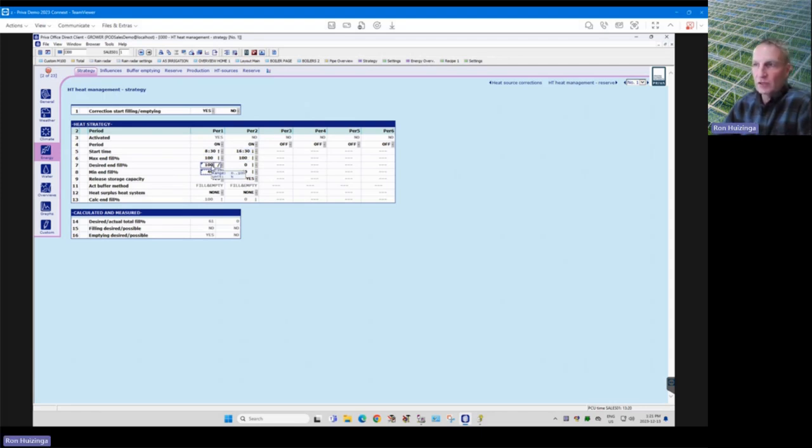Basically, that means that you're filling your buffer tank at a continual rate from the start time to the end time, and not going at 100% full speed of all your boilers and filling your buffer tank up by lunchtime, and then having no room for CO2 in the afternoon. So you'd want that slant there, so you'd ramp the boilers from the start time to the end time. Okay, thank you, Ron. You're welcome.